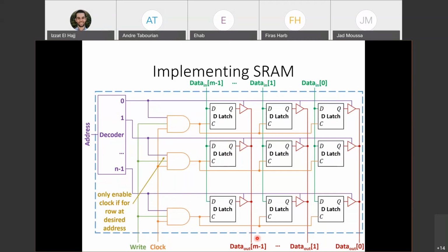Okay? So the value that they're going to read is not going to be reliable because I am changing that value in the middle of the clock cycle. So that is what I mean by we cannot read and write on the same clock cycle, because if we are writing on that clock cycle, the value that we are reading is not going to be reliable. So we shouldn't try and read it. Okay, clear now?